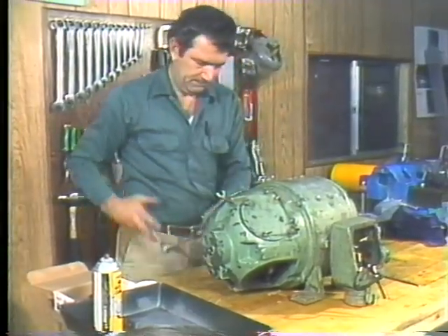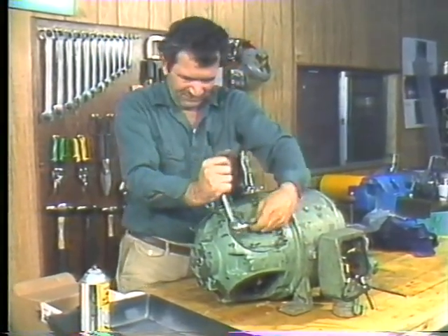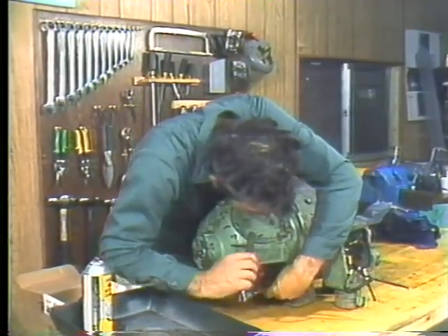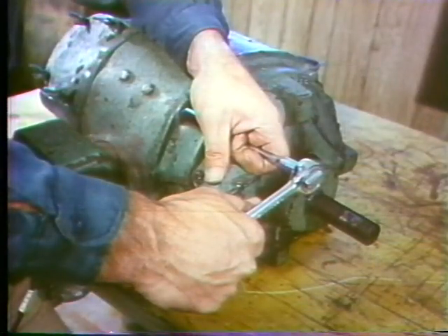As you work, keep an eye on the crack between the end bell and the frame. Try to keep an even space all around. Adjust your tightening of the bolts to compensate if it seems to be uneven. All right, now do the other end bell the same way.